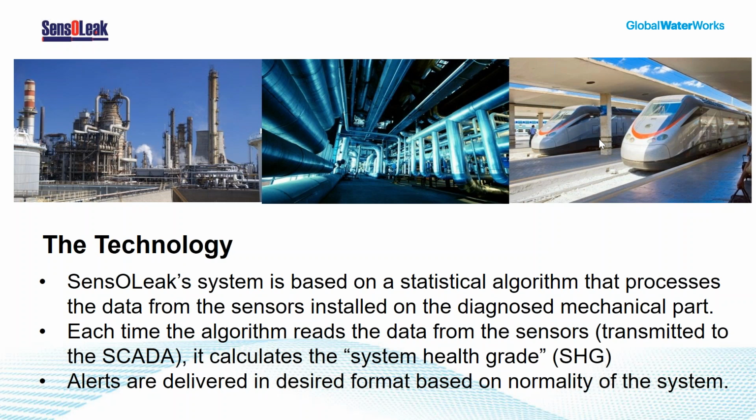And in order to determine the normal behavior of any equipment, especially a pipeline, we need to take a lot into consideration. So usually we measure for the online operation pressure and flow. We look for correlations. One thing that differentiates us from other leakage detection or algorithm-based companies is that we're trying to explain one variable or changes in one factor by the others. And that's how we manage to clean the noise, and that's why we don't have any false alarms.